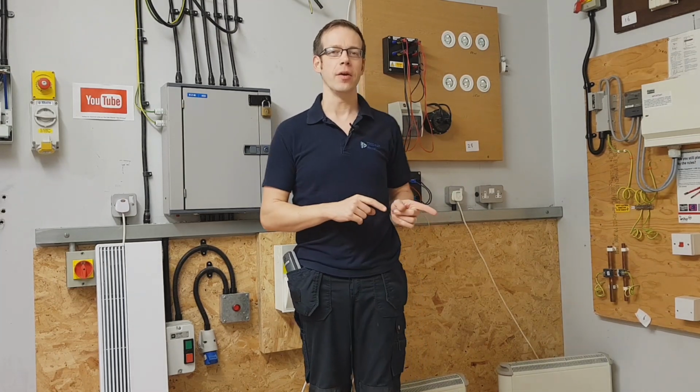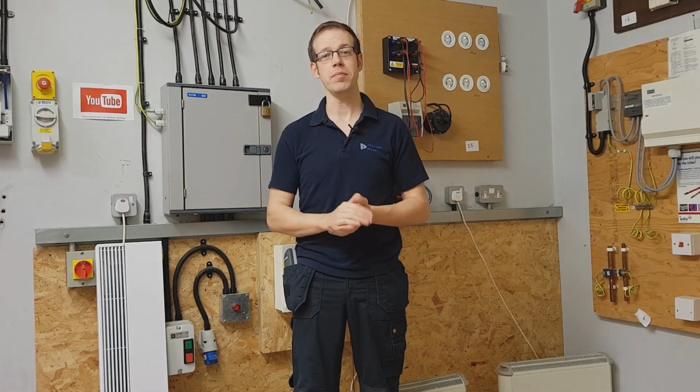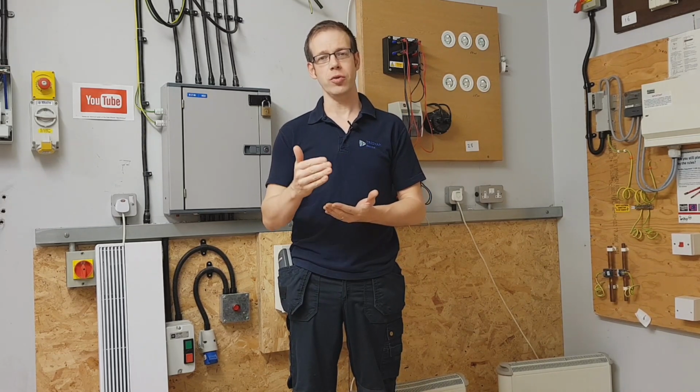Now in a previous video we saw that if you have what we call a balanced load on a three-phase system, that means the same amount of current in each one of the conductors, then there is zero current in the neutral. And in fact we saw that you don't even need a neutral conductor in order for that circuit to continue operating, because there's literally nothing flowing through it.